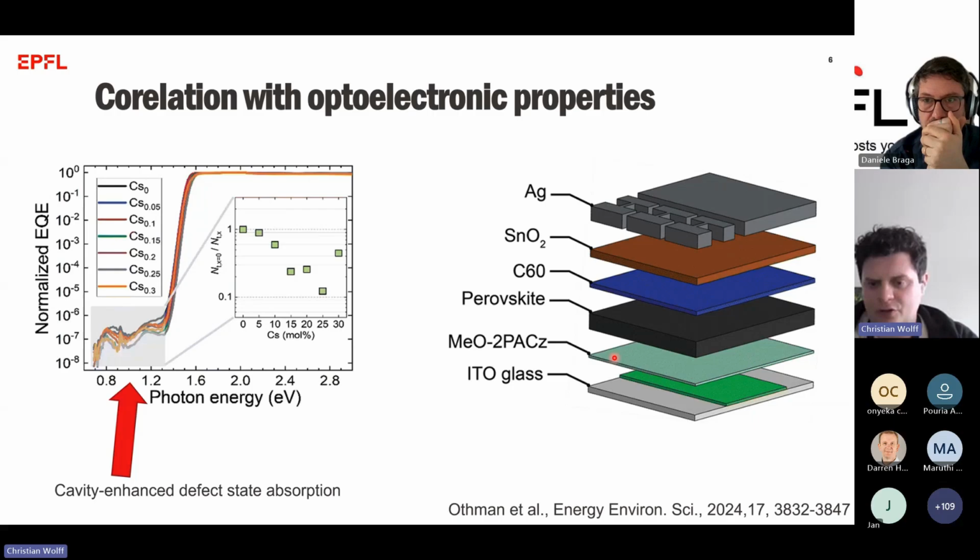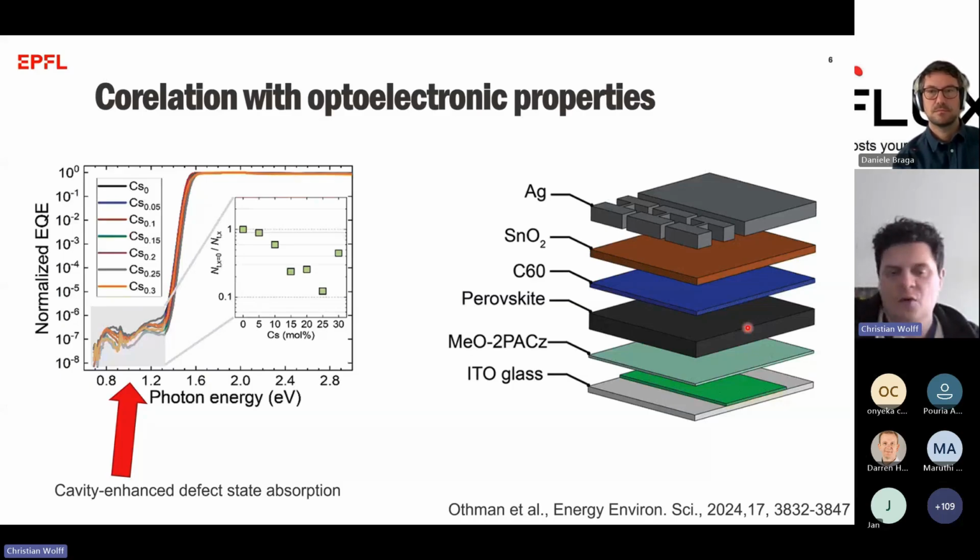And then in a second set of experiments, I think it'll be interesting to see how tough or not so tough bonds at the bottom and top interface impact the lamination and delamination behavior in thermal cycling. Because for me, it is not so obvious whether you necessarily want extremely tough interfaces, or some sort of molecular spring that compensates for some of the strain that naturally occurs. But it's an important question.